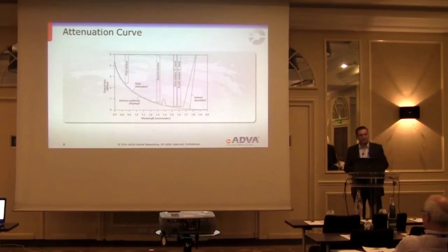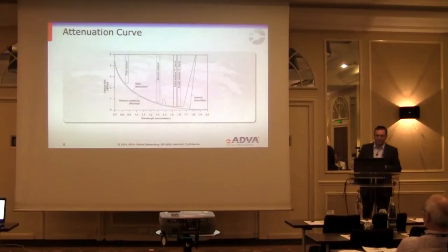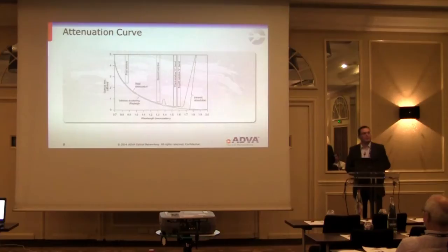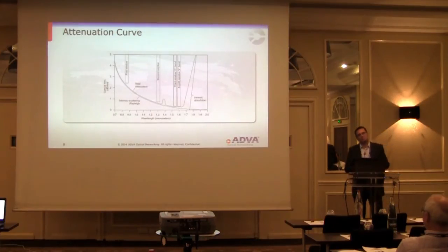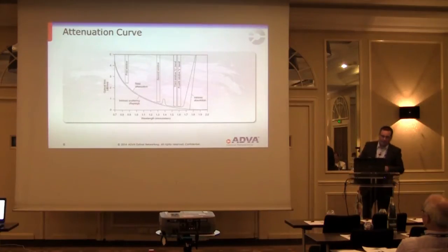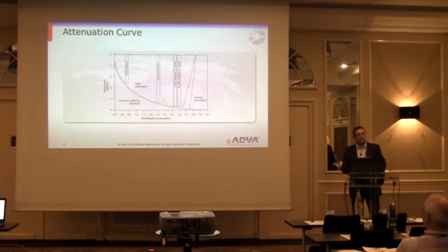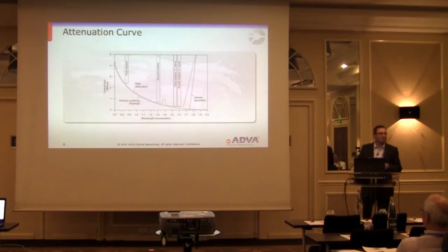This is why it's still used only in-house, but it's cheap. So a couple of years later, industry figured out how to do the same in the 1310 nanometer window. That's the second window. It's cool because you can travel already longer distances. So it can go up to a couple of kilometers maybe. It's lower attenuation there. But there's a fundamental issue in this window because you can't do WDM, so multiplexing multiple wavelengths there.